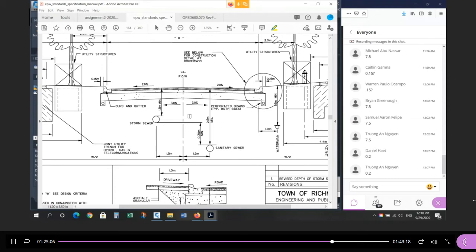Sewers are always straight lines, especially for small local sewers. There are some big sewers that have some radii in them, but generally speaking, that's unusual. It's a really big pipe. This is just the local sewer system, storm and sanitary, small pipes. They're always going to be straight lines. How do you deal with when the center line is curved, but the pipe isn't? We'll get into that in a moment.